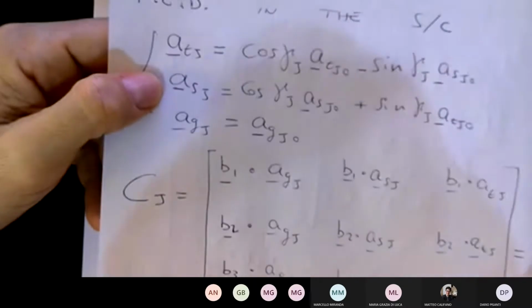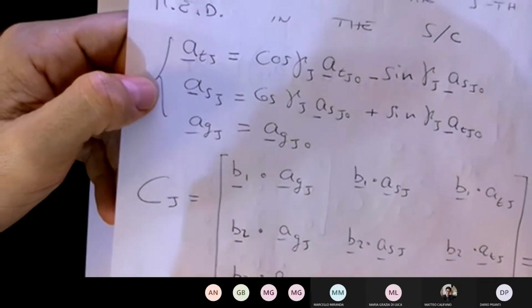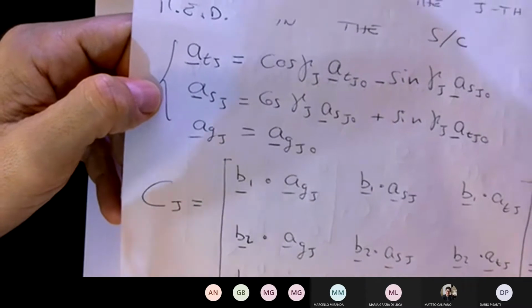My suggestion is that we start building, forgetting about the feedback loop, the blocks to simulate the momentum exchange devices, which really starts from, well, the first thing to do would be implementing the position of the axis of principal inertia attached to the momentum exchange device, and then build all those matrices that we have seen for the equations. Sounds like a plan?